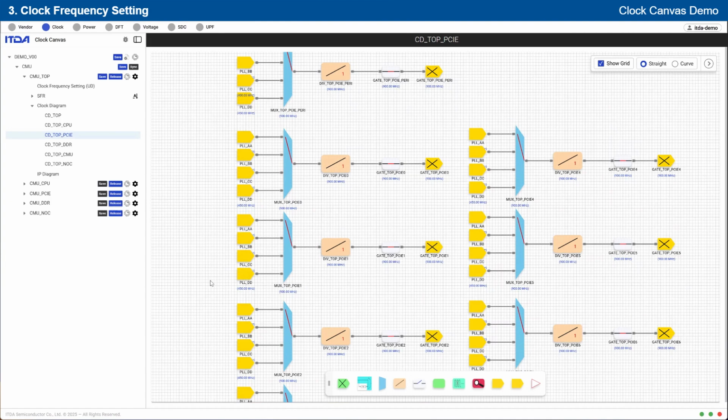The challenge of clock system design is not just to create a single MUX or a single divider. As I experienced in mobile APs, there exist hundreds of clock MUXes and hundreds of clock dividers, and more than thousands of clock gates. What's really difficult is to ensure the data consistency across all these components, understanding how they are configured and keeping everything in sync. Again, SoC is not about design, it's fundamentally about data handling.